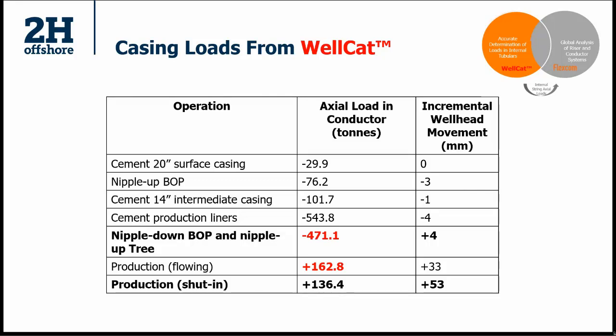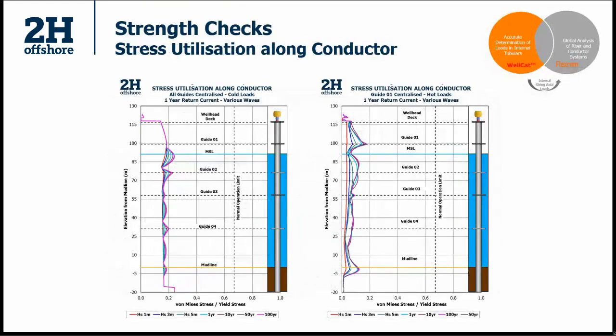And these wells were hot enough to actually put the conductor into tension when the well was put onto production. That's how hot these wells were. So we took this data and applied it to a FlexCom model of the conductor to look at the marine analysis and the effect of the environmental loads on it simultaneously.